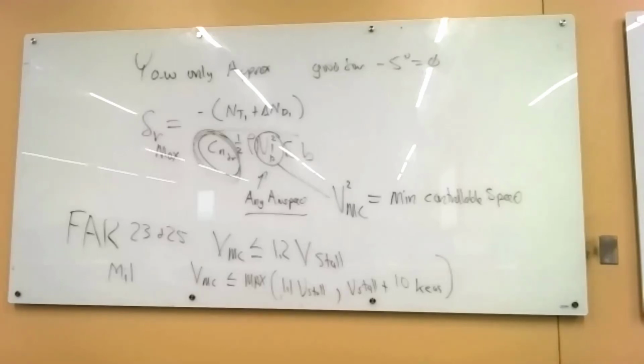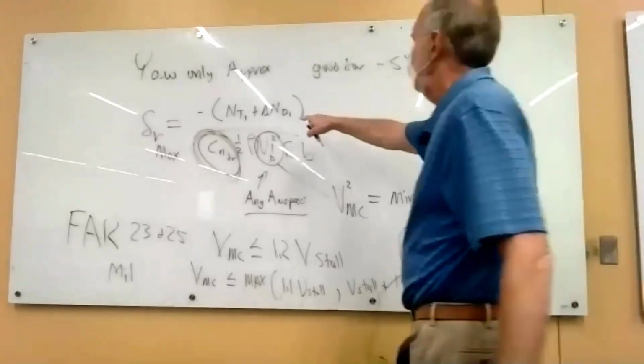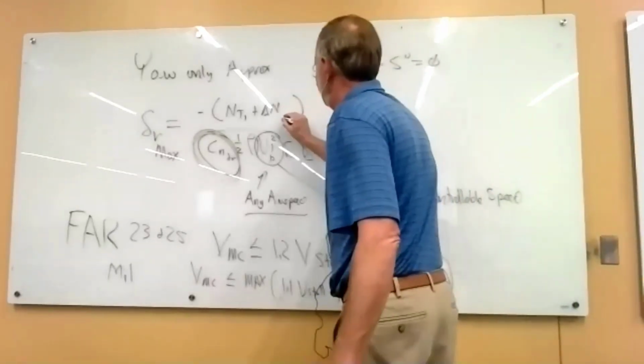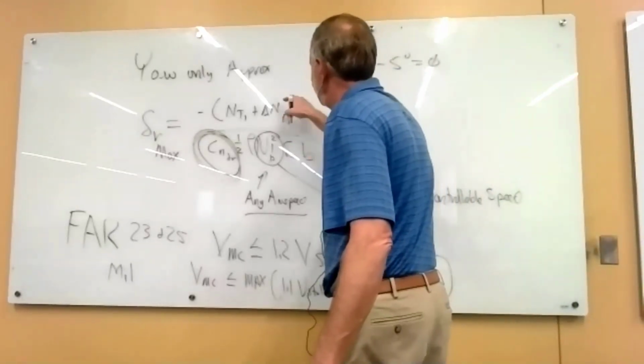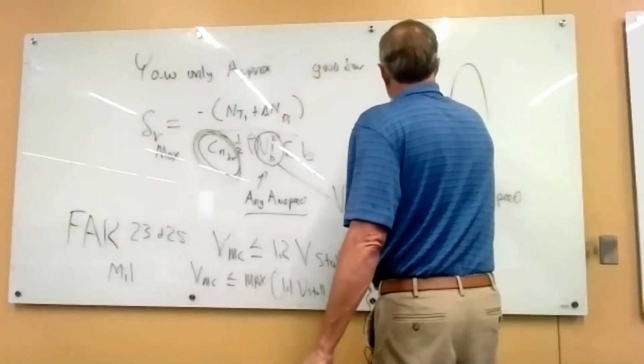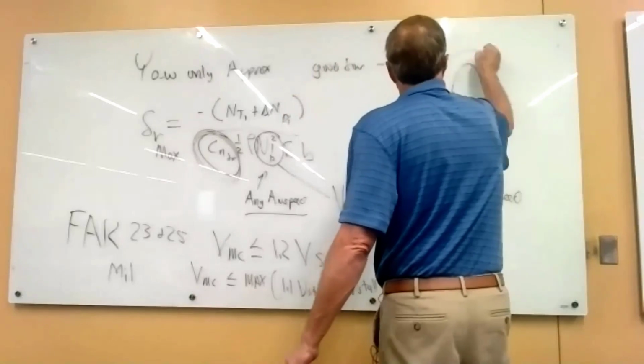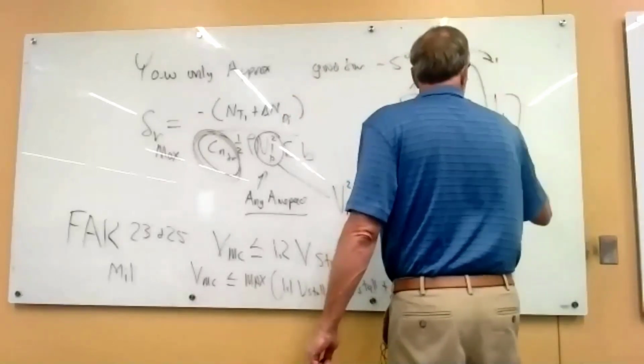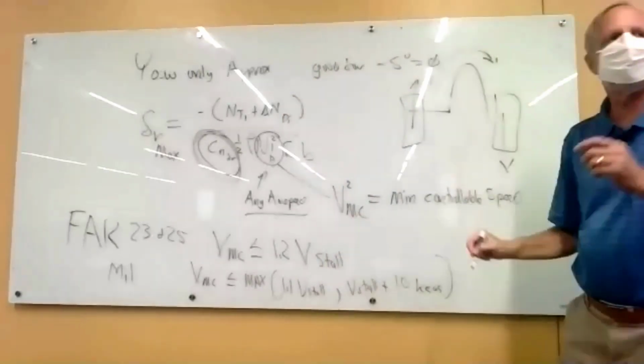The numerator? Oh, both of those cause the same yaw, right? This is the drag, this is subscript. This is the yawing moment due to that drag. So the thrust causes a yaw like this, and the backwards drag causes a yaw in the same direction.